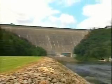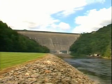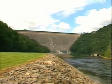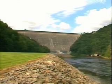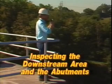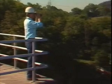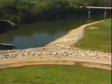This part of the video covered deficiencies commonly found on the downstream face. These deficiencies are described in more detail in the text. Now let's discuss inspection of the downstream area and the abutments. These areas may first be observed from a distance, using binoculars. Then, if possible, on foot.